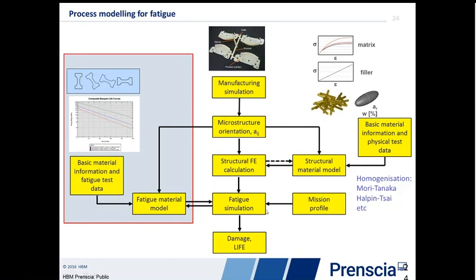So I'm bringing in basically orthotropic or anisotropic stresses, and then I have a fatigue model that's looking at a critical plane analysis, either in plane or full 3D, looking at different directions. And then with the fiber orientation information, I can go in and choose the appropriate stress life curve to go off and do the fatigue calculation.